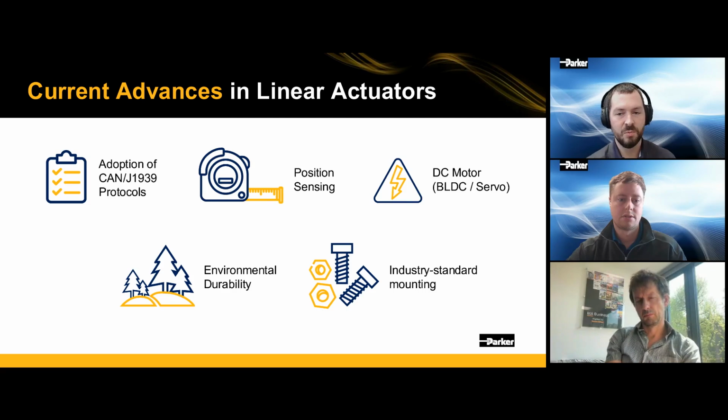So you're seeing more and more linear actuators have industry standard mounting like NFPA. So bolt-on ends, threaded rod ends that allow you to get custom clevises or greasable spherical ends to make your EMA or EHA bolt into your application, versus having your application work around the constraints of the actuator.